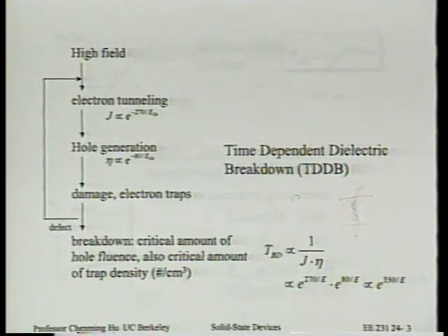The current will be so large that the inductance and the IR drop make it very difficult to figure out what actual voltage is applied across the oxide. Ten picoseconds and maybe 1 ampere going through this very small capacitor. It really takes that much current if you try to break it down in a very short time. So actually information to answer that question is not available.